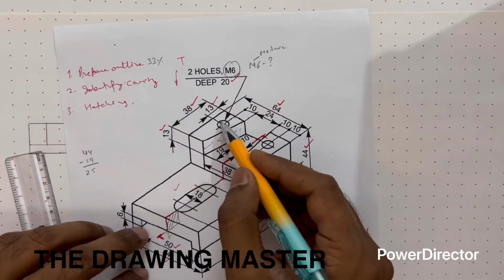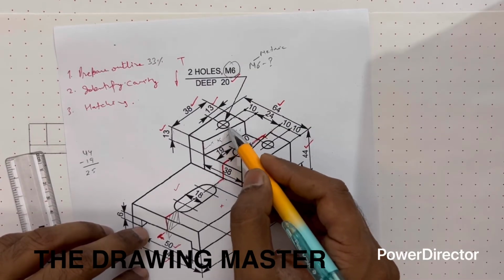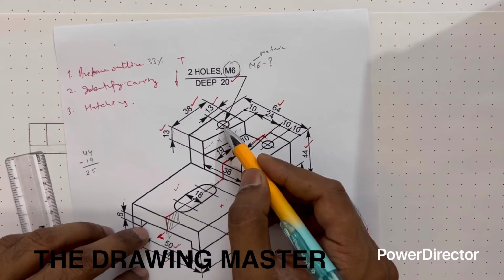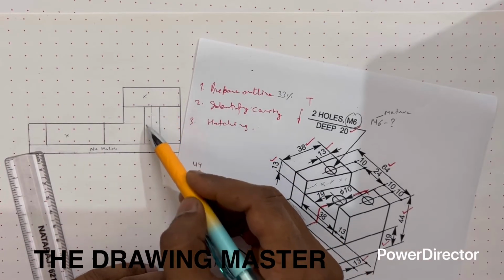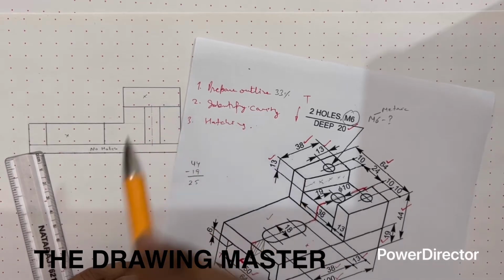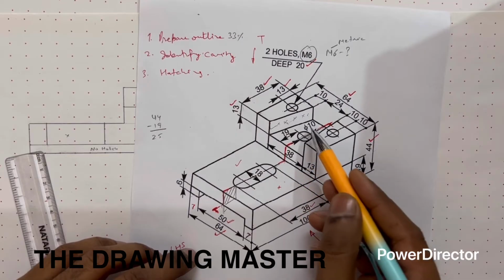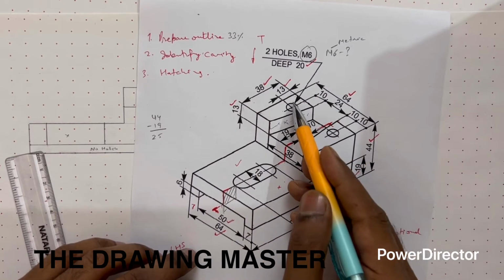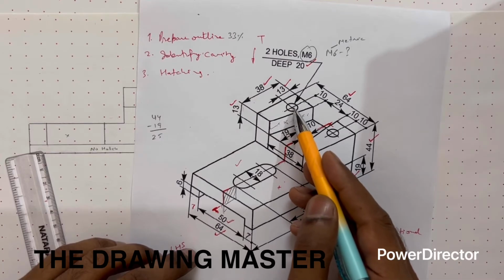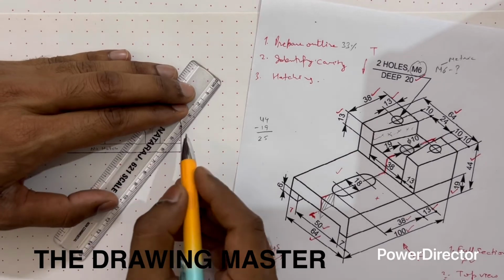So basically this 6 mm dia will be unaffected because the cutting plane is here. It will remain hidden, but in sectional view we are not interested in drawing the hidden lines. So here we will not show any hidden line. The reason is we are talking about this particular section of the object. So that's why we are not interested to draw this hidden line. So in the remaining area we'll do the hatching here.